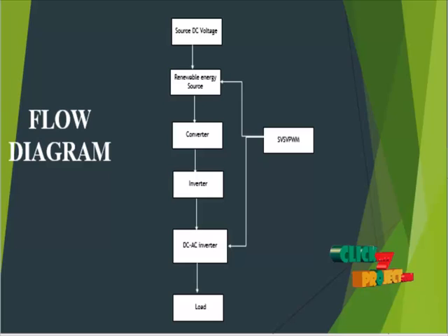The new topology achieves a reduction in the number of power devices and voltage stress in comparison between the two inverters, and a 7-level inverter is implemented using the proposed topology with fewer components. Since voltage deviations cause large harmonic distortion in the output voltage, a voltage balancing circuit is used inside the capacitors of the multi-level inverter by using switching capacitor converters.